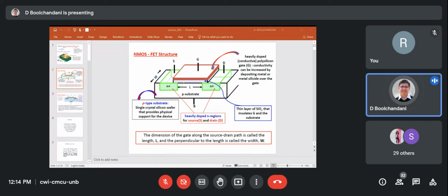And further, what we are seeing here is that the gate region extends from this to this, and your intended channel length was from this end to this end. But when you are fabricating a MOS transistor, what happens? You have a P-type substrate, and you want to convert this into N-type, and again this into N-type. You either do a diffusion or an ion implantation.